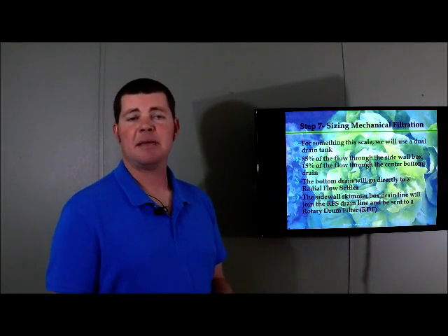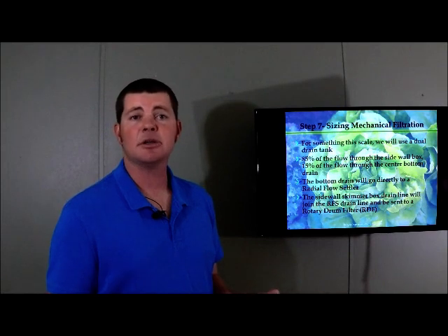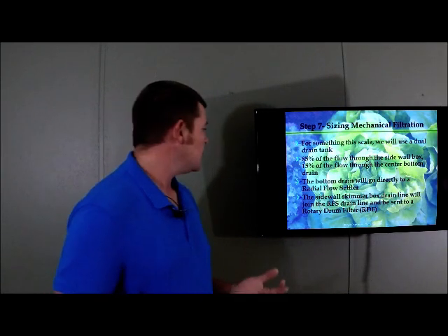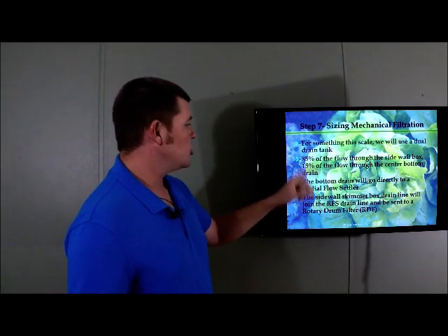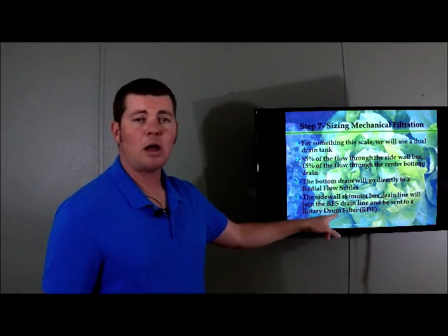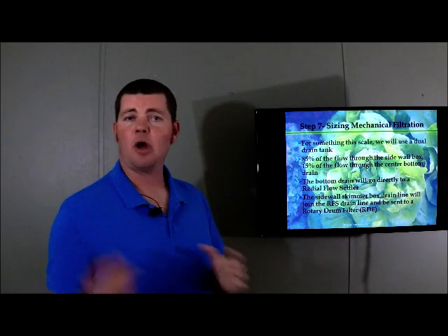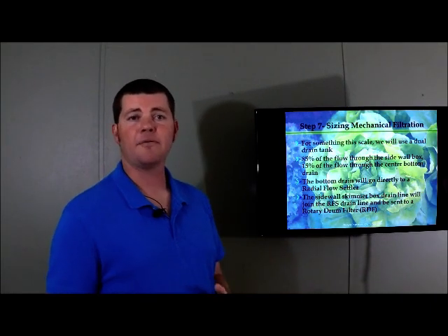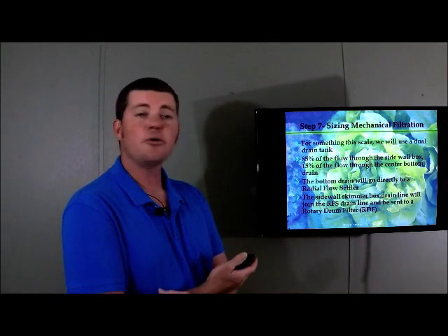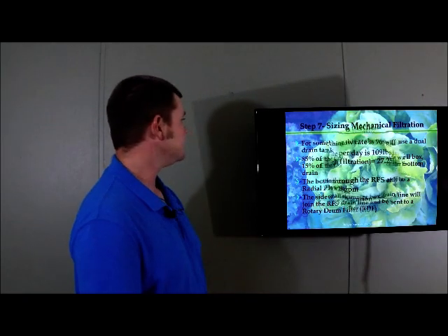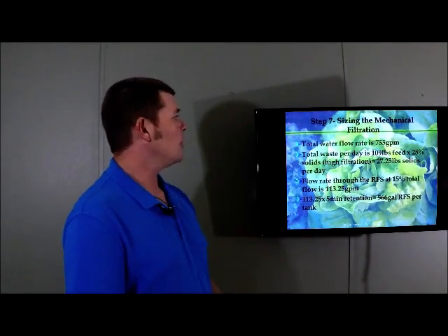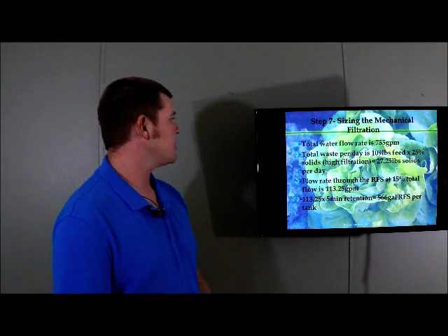up to 50%, maybe 70% of the solids, depending on conditions, that water line is going to join the water line that just came out of the sidewall of your tank that has 85% of your flow, and all that water, 100% of your water flow, will go to the rotary drum filter. Total water flow rate is 755 gallons per minute.